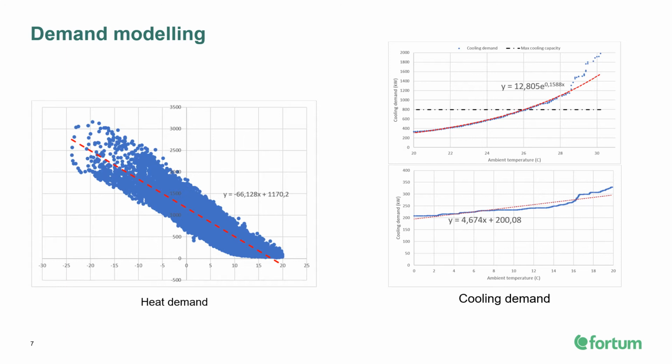The cooling demand was a bit trickier. There is no existing cooling data on the buildings other than that the helium production unit requires a constant cooling. The designer of the network, Sweco, created a cooling demand duration curve, which then was matched with historical temperature data from the last 5 years. And then with that, a piecewise function was created for the cooling demand.